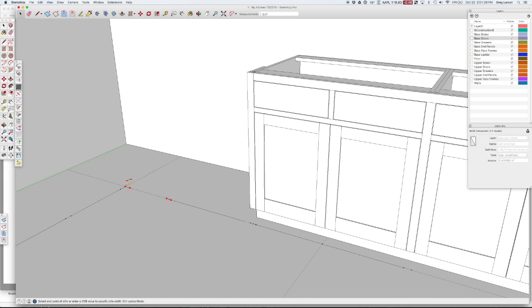And we're going to draw another style here. And that is, oops, I made a mistake. So notice it's only giving me right choices for the right side. So I made a mistake here because this is the left side. If I drew it like this, it would think that the cabinet was facing the other direction.